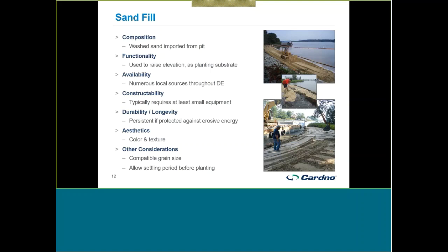And then just in terms of other things to think about, it's important to have compatible grain size. Sand that's too fine a grain in an otherwise coarse environment is more prone to being washed away and transported off your site. Therefore, it's not really going to serve its function in the long term as much as you want. And depending on your situation, it's recommended to allow at least a couple tide cycles to go by so that your sand settles in place.